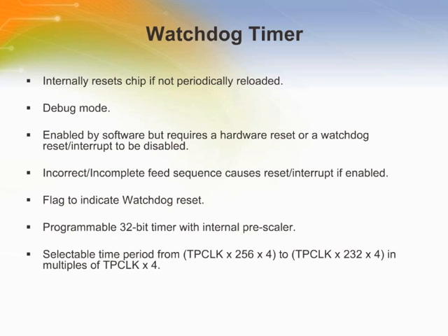The purpose of the watchdog is to reset the microcontroller within a reasonable amount of time if it enters an erroneous state. When enabled, the watchdog will generate a system reset if the user program fails to feed or reload the watchdog within a predetermined amount of time.